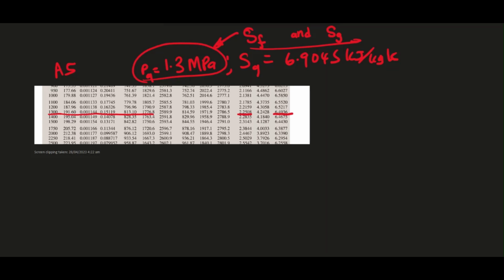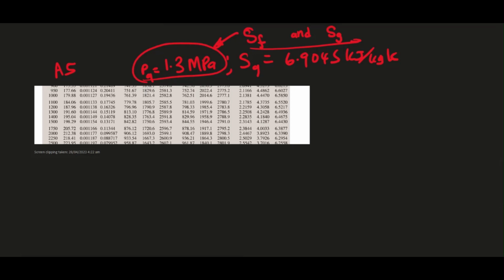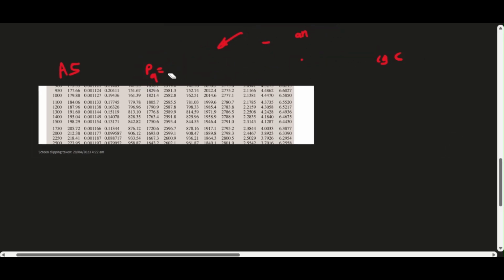Therefore, you guessed it, we are looking at a superheated state. So our values should be collected from the superheated region, at 1.3 megapascal and at the given entropy.